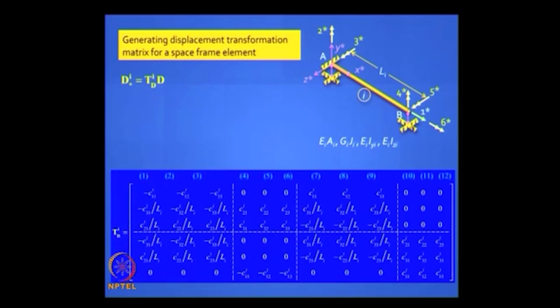So here what we did was we picked up whatever we learnt from the plane frame. You are familiar with the plane frame element? You are familiar with the grid element? We just had to add some more constraints for the horizontal bending.